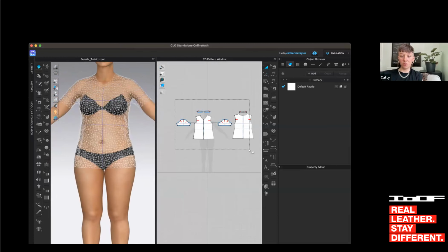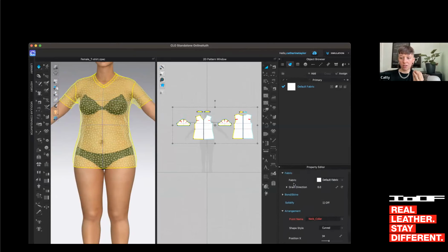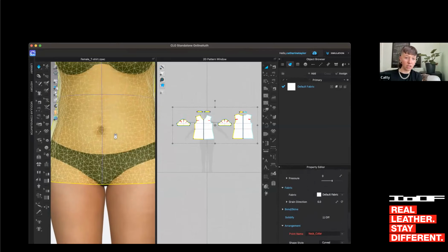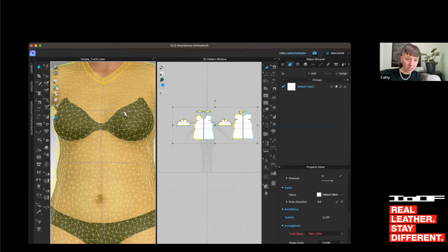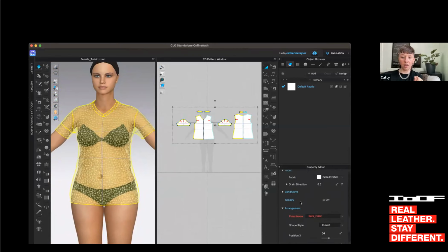Sometimes digital fabrics will be a tighter mesh, which basically means more detail. So this at the moment has got a particle distance of 20, which basically means the line from there to there is 20. What you don't want to do is increase it to like 5.